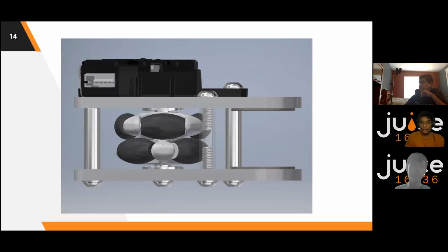All right. Next question was, how much better is it to have 3 wheels for odometry? Niket could address that. Yeah, so you can do either 2 or 3 wheels, right? But what the third wheel traditionally does is it'll help you calculate rotation easily. Although we only had 2 wheels, so we were able to work around this by using the IMU to calculate our rotation, which, in my opinion, was accurate enough for us. But if you wanted even more accurate rotation, you could have 3 wheels.